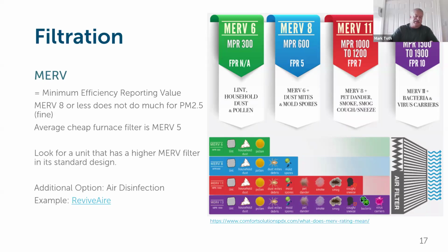And then you need to have a very high MERV rating filter after it to catch those pieces. So we're not just now blowing, we'll call it dead material around in your air. We want to actually kill it and then take it out.